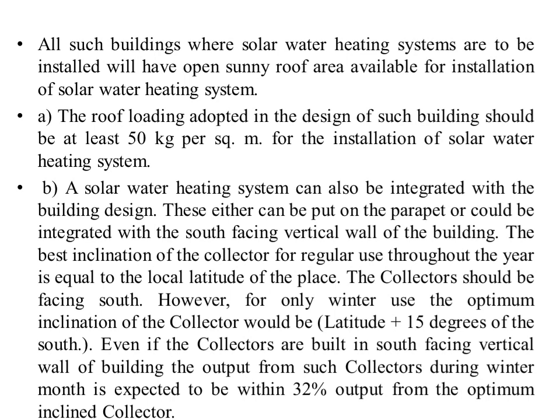The best inclination of the collector for the regular use throughout the year is equal to local latitude of the place. The collector should be facing south. However, for only winter use, the optimum inclination of the collector would be latitude plus 15 degrees south. Even if the collectors are built in south-facing vertical wall of buildings, the output from such collectors during winter months is expected to be within 32% output from the optimum inclined collector.